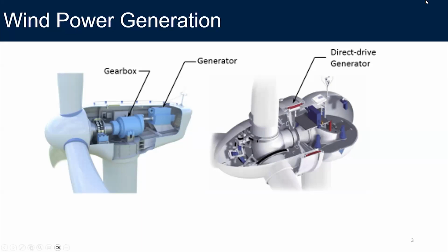However, the advantage of going into direct drive machines is the elimination of the gearbox itself. So although there's no weight reduction benefit in this type of application, the reduction in maintenance requirement helps with the application, and also the construction as well.